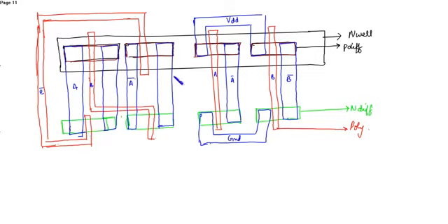So now in order to connect this A to this A, we can connect from here. Because you have to keep in mind, we could have done it directly, but here since the other metal layers are there, they will overlap. So these metal layers shouldn't overlap.